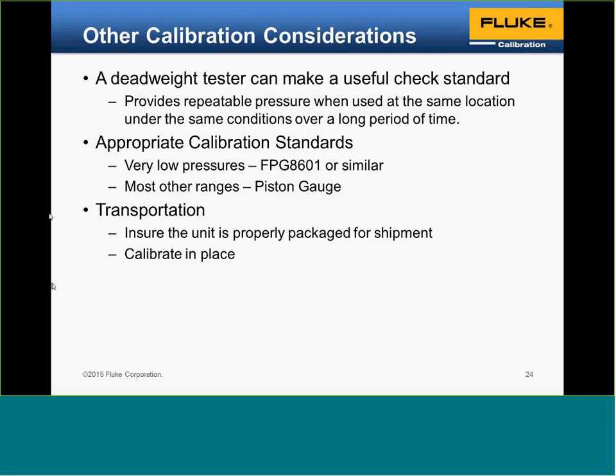So, regarding calibration, many have found that a deadweight tester can make a useful check standard. The measurement uncertainty of the deadweight tester may not be sufficient to actually calibrate the pressure controller. But the deadweight tester provides a repeatable pressure that's very stable when used at the same location under the same conditions over a long period of time.